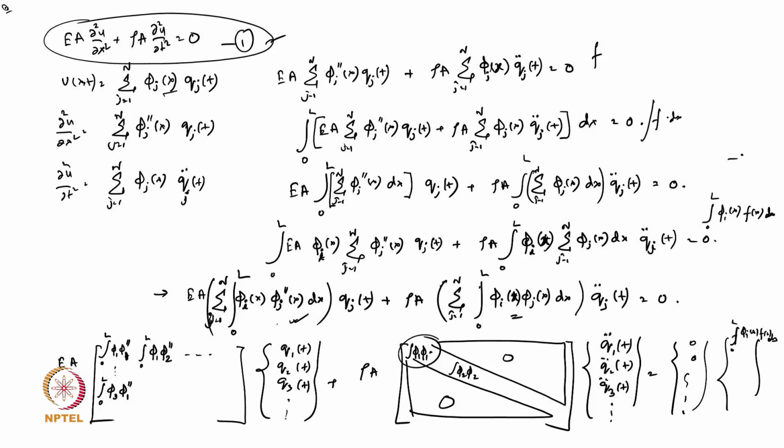And the third case, which is the finite element, there you have to do integration by parts again, because there you are not allowed to do this type of integration where you have one with phi x and another with phi double dash x. You have to make both equal. So you will perform integration by parts one time, so that you can reduce the order of one and increase the order of the other and make them equal. So that will become your finite element.